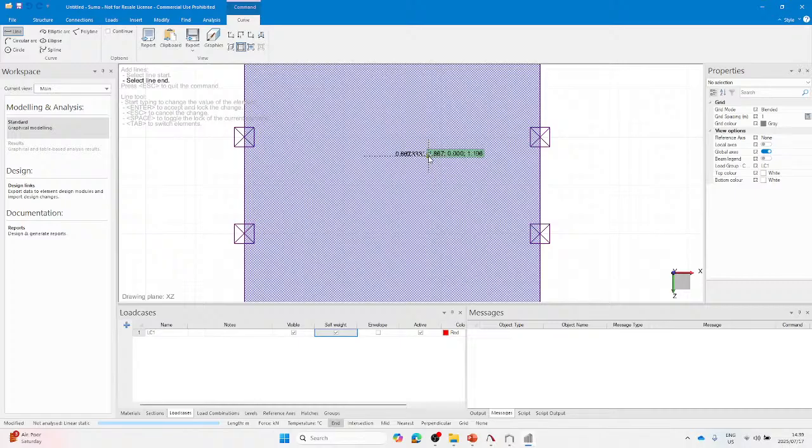where I want to place my area load. So then I'll press tab, and it should be 0.6, because the two shells that I have applied the load onto, the one is 0.3, the other one is 0.3. That is why we're going with 0.6. And tab, and I want to make my angle 0, and you will see that line defined.